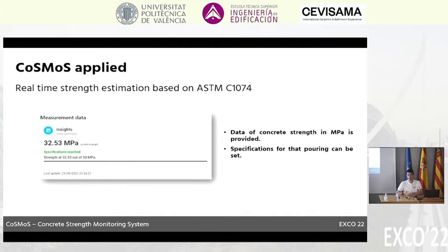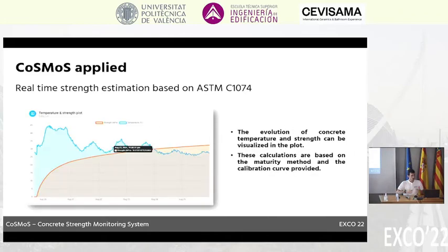They know how much resistance or strength the structure needs to acquire. So they are going to be looking into that, and when the application tells them, they are going to be able to make decisions around it. And basically, that's the information they see. Here, the blue graph is the temperature evolution for a concrete element, and then the one in orange represents the strength evolution in megapascals.